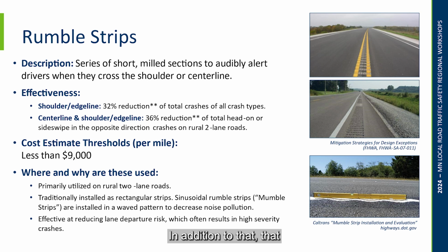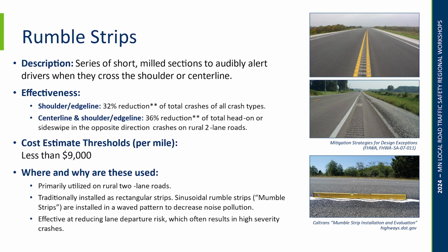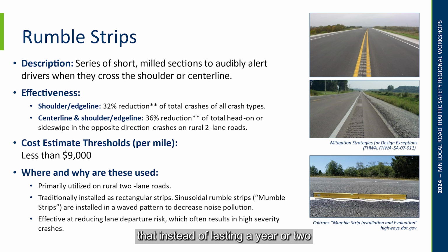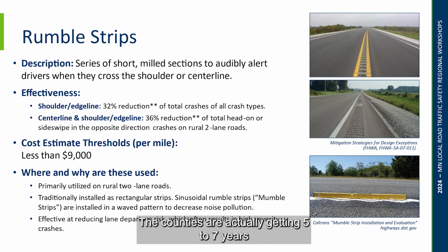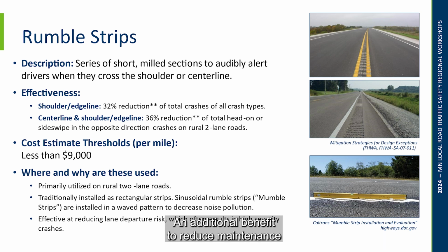In addition to that, counties that have done this have shared that because the snowplows can't cause damage to the pavement markings, instead of lasting a year or two before they have to be replaced, the counties are actually getting 5 to 7 years of service life out of the edge lines, and that's an additional benefit to reduce maintenance costs.